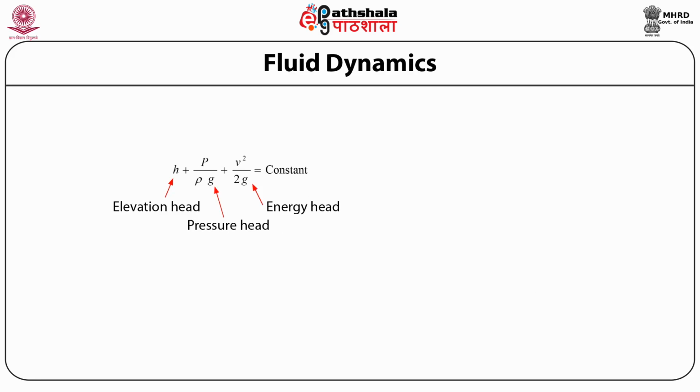Now come to fluid dynamics, the third category of fluid mechanics. Fluid dynamics deals with the study of flow and the energy involved in causing the flow. The principle of conservation of energy states that energy is neither created nor destroyed, and the total energy within a system remains the same. That means the different kinds of energies, mostly potential energy, kinetic energy and pressure energy, the major three energies at any point, remain constant in a system.